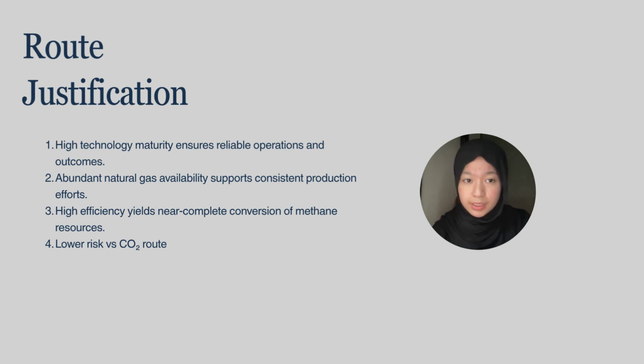While SMR is an endothermic reaction, the overall plant is thermally efficient because we can recover the exothermic heat from the methanol synthesis reactor to preheat our feed streams, compared to CO2 routes, which are still maturing and require complex hydrogen generation systems. This conventional route offers the most pragmatic, reliable, and justifiable design for current industrial applications in Malaysia.